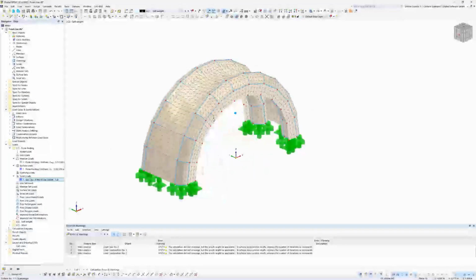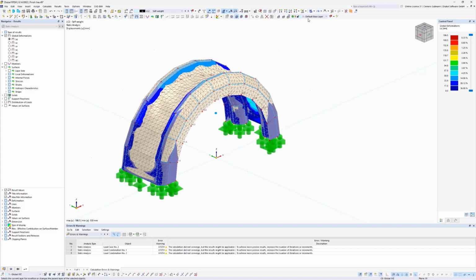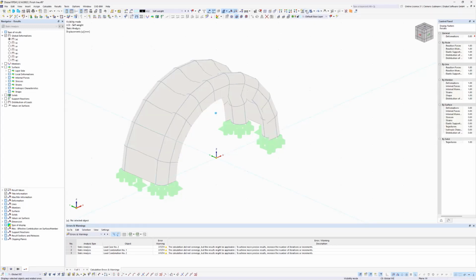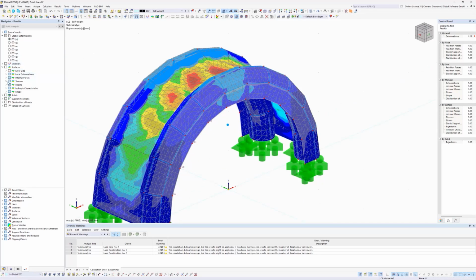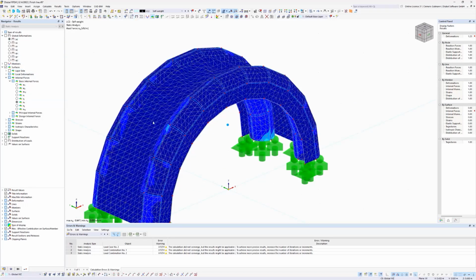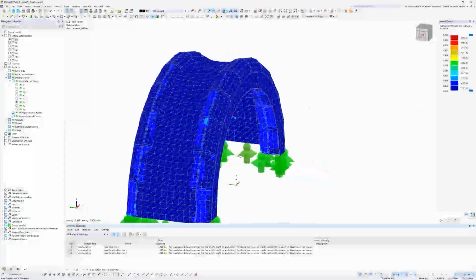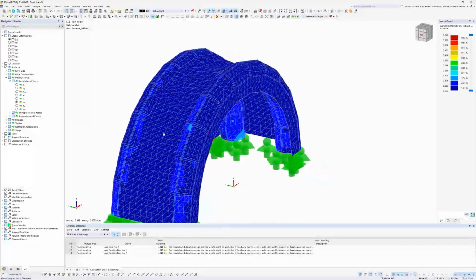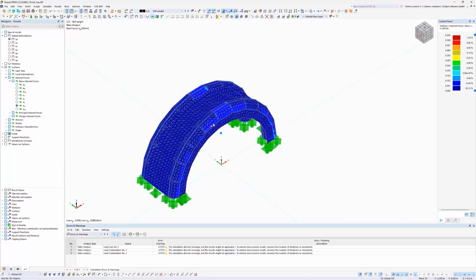It's because the membrane folds and it gets creases and so on. If we take a look at the results, oh wait, wrong button. Here, which are highly likely not correct, but still you can see some things. So most of the membrane has no tension, and it fails on the compression, so it's unstable, or it's not stable, let's say.